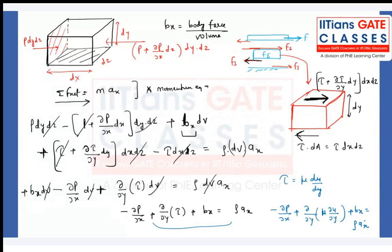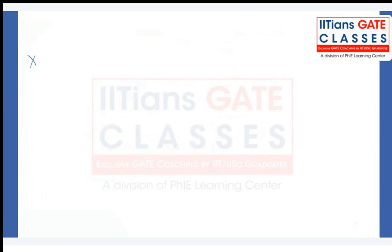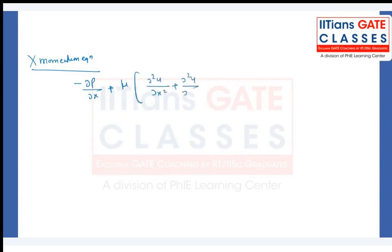In a bigger picture, when you write the x momentum equation and do the complete derivation, you will have minus dou p by dou x plus mu into dou square u by dou x square plus dou square u by dou y square plus dou square u by dou z square, plus bx, that is equal to rho into acceleration.